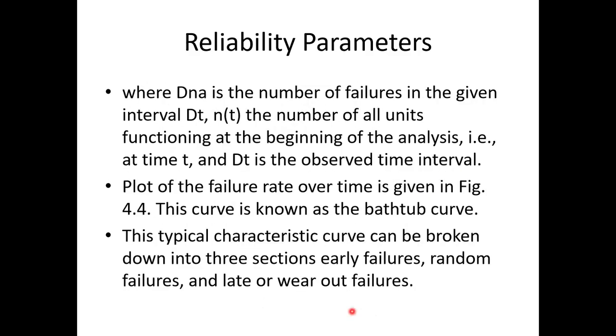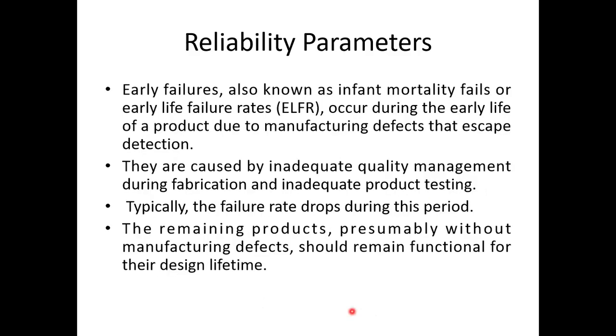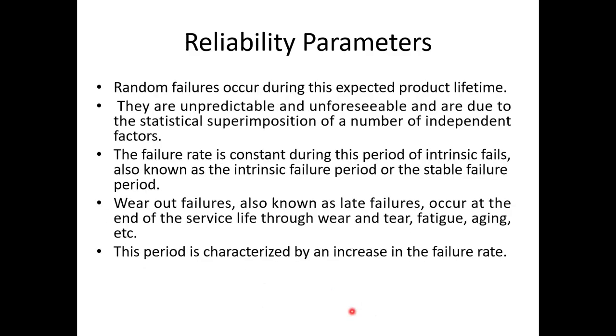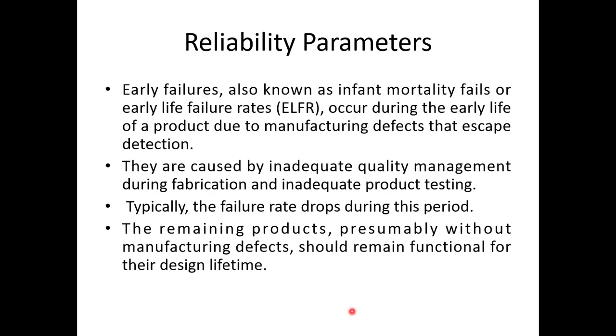Okay, so here we will see the three failures: early failures, random failures, and wear out failures. Early failures are infant mortality failures, failure rates occurring during the early life of the product due to manufacturing defects that escape detection.